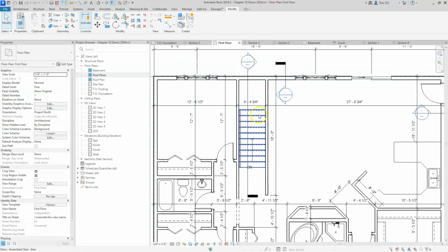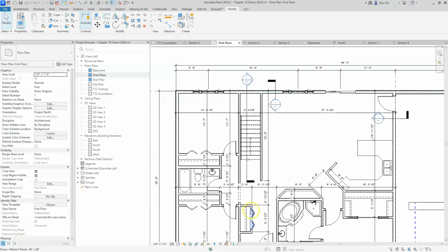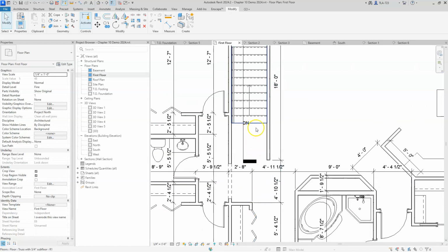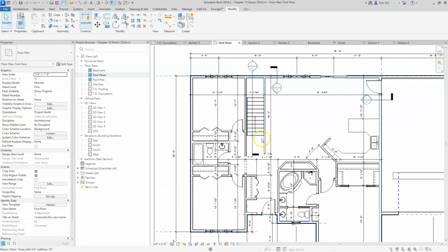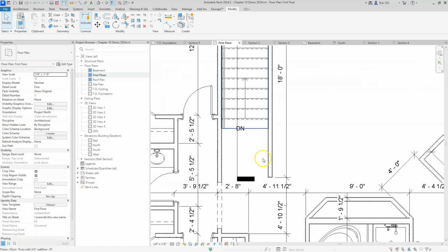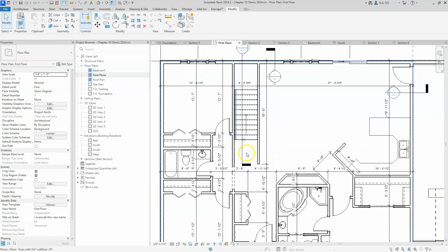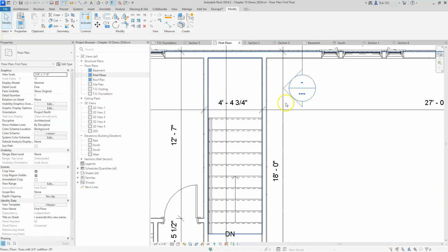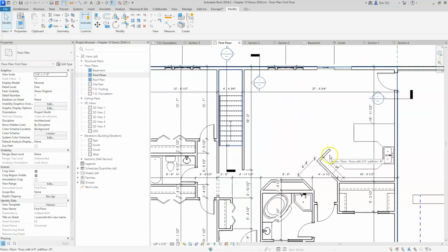It might make more sense if I don't want to do that landing at the bottom and that whole L-shaped stair thing. I do have plenty of room here to create a different stair, don't I? I could add at least the number of treads that are at the bottom of this thing. I could add 3 treads and still have plenty of room for this hallway right here. So that's probably the best strategy rather than messing up my floor plan and having to carve out of this living room with a little chunk right here. For now, we're just going to leave it.